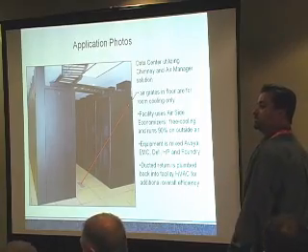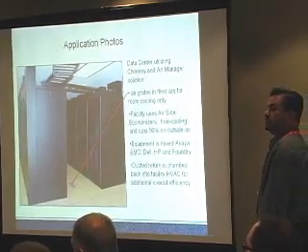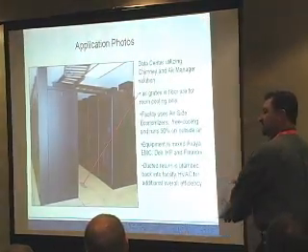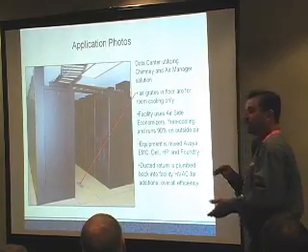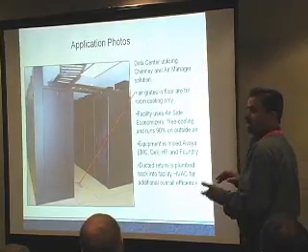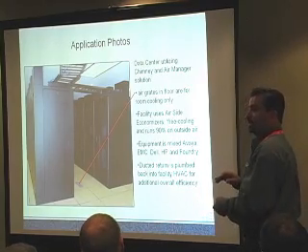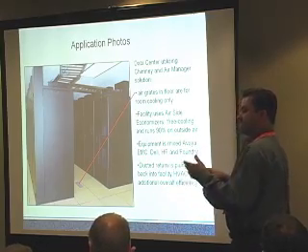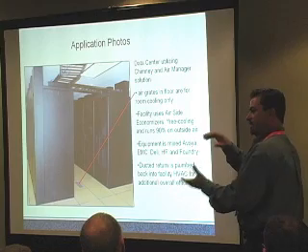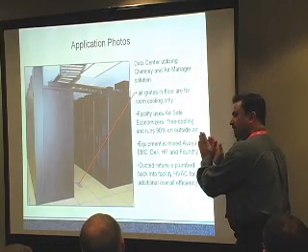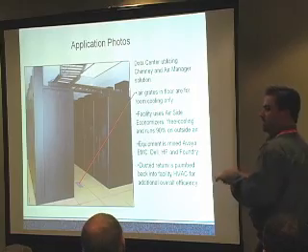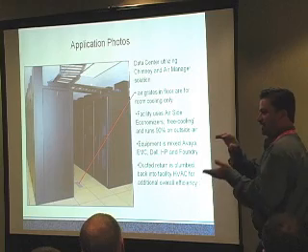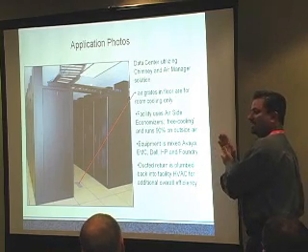This is in Pittsburgh. Is there a big problem when you open the front door? Actually, no. The front door is a mesh door. Okay, so it's not relying 100% on that. It's still getting some, but what it's doing is dropping the air intake approximately 5 to 8 degrees, and sometimes even more than that. But it's not relying 100% on that airflow going through there. It's still getting a mix of the room. Instead of the mixing happening in the cold aisle, the mixing is happening inside the cabinet right in front of the air intake of the equipment. Usually there is a temperature increase from the cold aisle through the mesh door right to the air intake. So we're kind of reversing that.